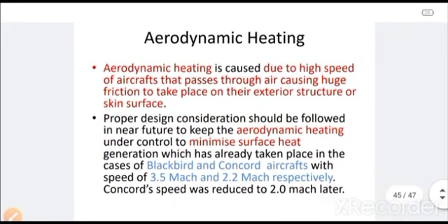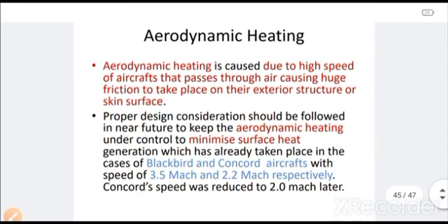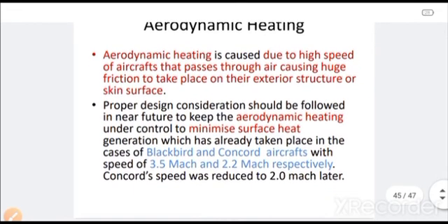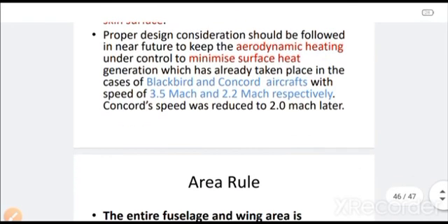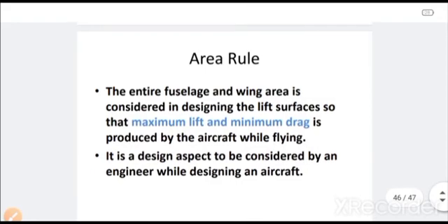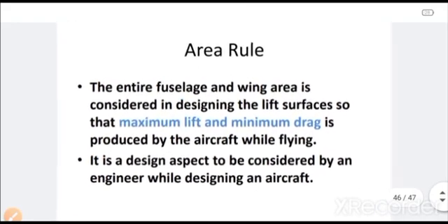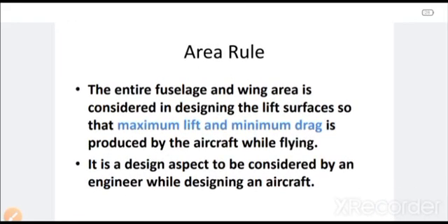So aerodynamic heating is basically a heating phenomenon that takes place due to the air friction when the aircraft passes through the air particles at that high speed, or above sonic speed. That is not the case at sonic level or subsonic level. That is only in the case of supersonic level.